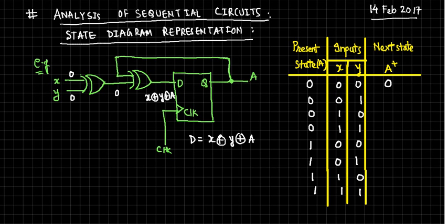Now let's go for this. Let this be 0 1. What is the output here? It will be 1. The previous data, what is A? 0. So it will be simply an XOR combination of all these three inputs, right? So do that: 1 1. It will be 0 1 0 0 and 1. Is that okay?